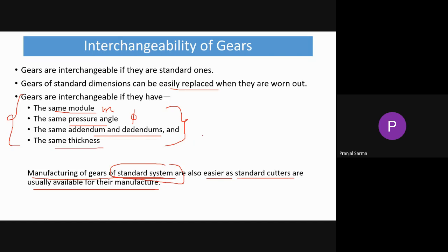Always go for standard tooth profiles. Depending on the requirement, it's possible to design your own tooth profile and, by following the law of gearing, have conjugate teeth.